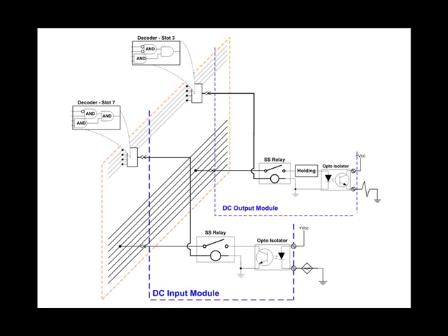If it is a DeviceNet scanner circuit card that has 32 words of inputs and 32 words of outputs, 32 individual transactions will take place one at a time on the backplane when the processor is collecting input images, and the processor will store these 32 words one at a time in 32 unique words in memory set aside for that slot. So we'll say that it was slot 5. It would be then I:5 dot word 0 through word 31, and each word has 16 bits.